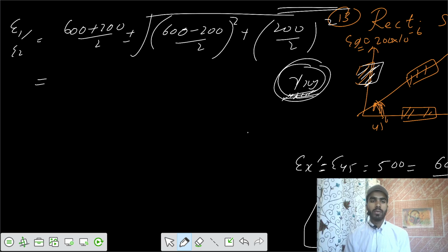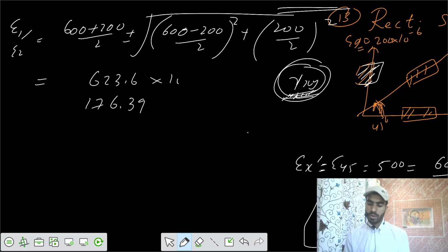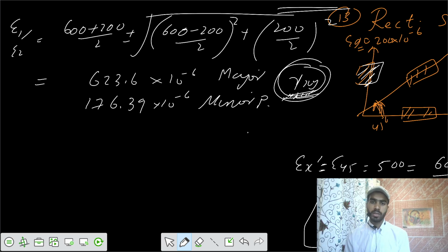So you get the major and minor values as 623.6 and 176.39, times 10 to the power minus 6. This one is your major, this one is your minor principal strain. So E1 equals this, E2 equals this.